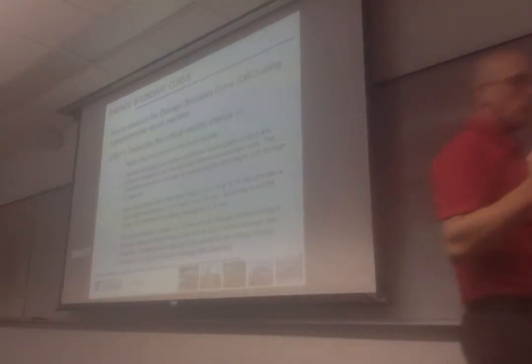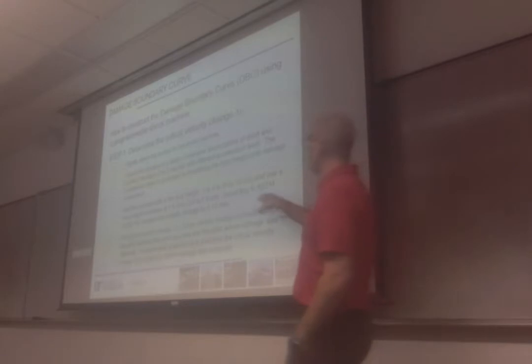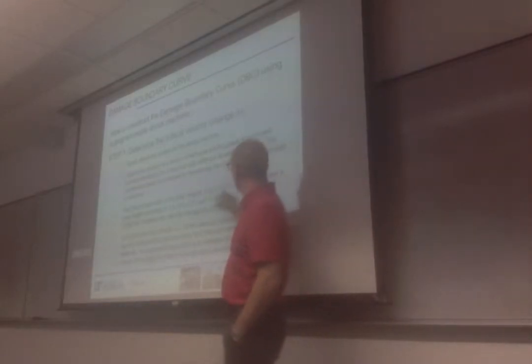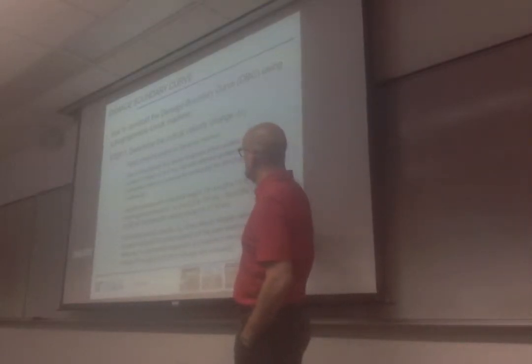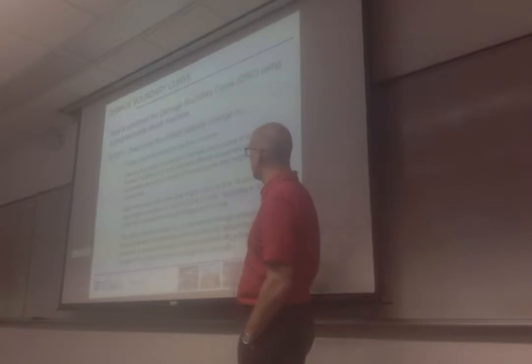In a way, the duration of the impact is controlled by the programmer themselves, so this is really a short time. What you do is drop from a low height and progressively increase that until you get damage. Initially you start the process with a low drop height, like 2 to 4 inches, and use a drop height increment of 1 to 3 inches typically.